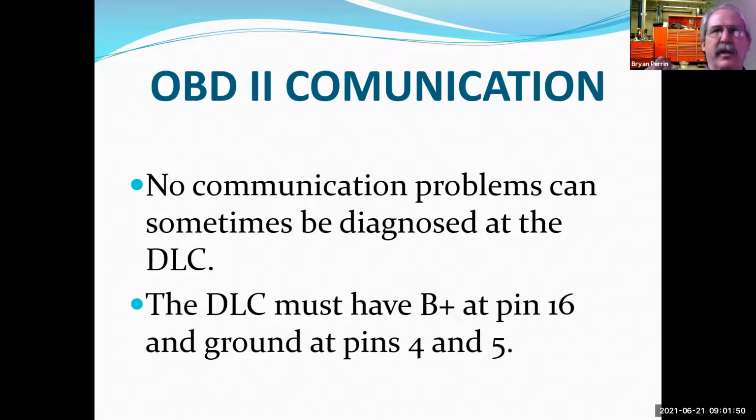So if you look at a connector and those 2 pins aren't longer, the connector on the tool doesn't meet the SAE standard. And where that creates an issue is not that it won't connect and work, but if it's not meeting that standard, a lot of times the pins are also thicker and they'll spread the terminals on the DLC. So when you hook up an actual certified tool that's actually made to the correct specifications, it won't read because of pin spread and you have a bad electrical connection. So something to look at if you're looking at tools.